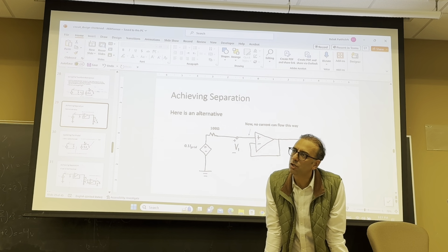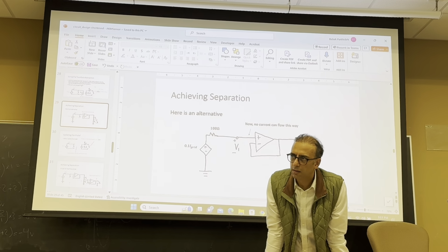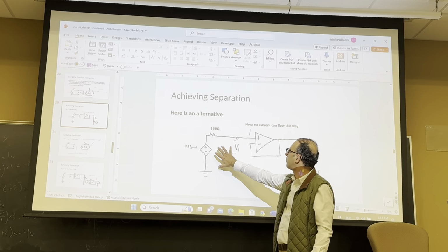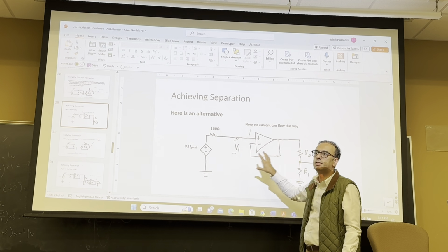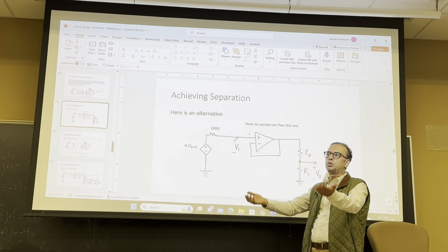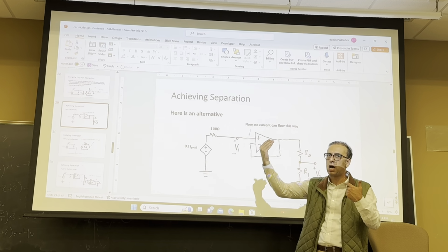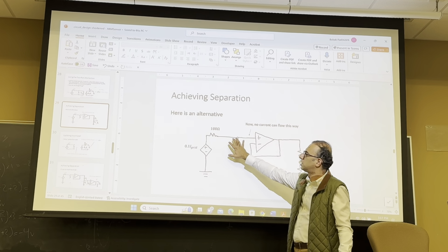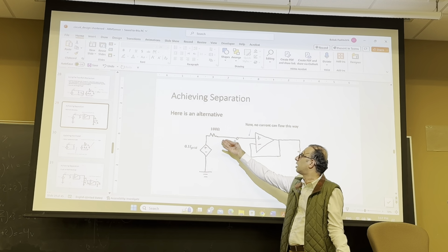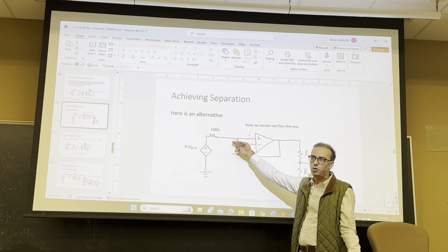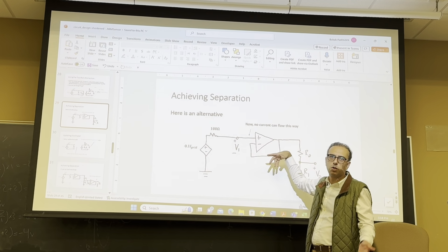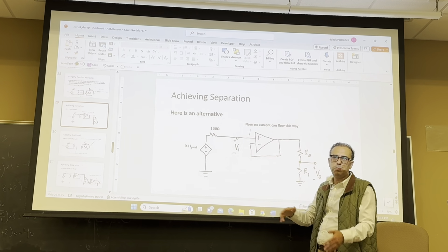Yeah. Essentially you don't load your detector. If you don't have this, everything that requires this interface is done through the sensor, including the power supply of the sensor. By doing it, as you said, with the high impedance, nothing goes through this, so it's just the voltage, and the power supply of this op-amp provides whatever power is required, maybe low impedance.